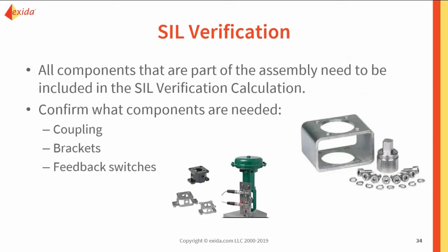However, with the SIL verification, as I said, we need to think of both all the components of the assembly and the final element integrated assembly overall. It's not just good enough for you to verify the valve, the actuator, the solenoid. You need to think of everything that could be included. Are you doing couplings, brackets, switches, filters, regulators? Any of that may be in this final element integrated assembly. You need to be considering all of those pieces of equipment.